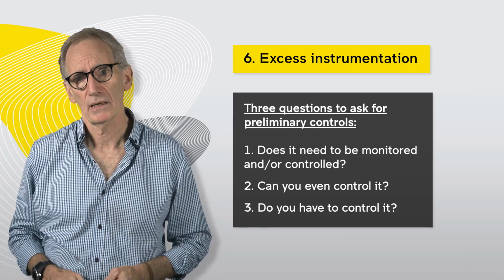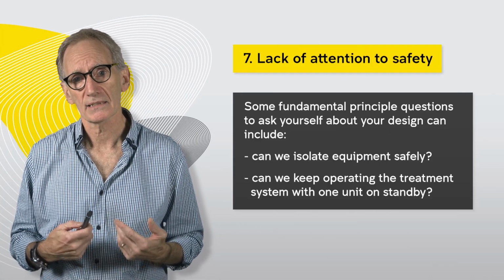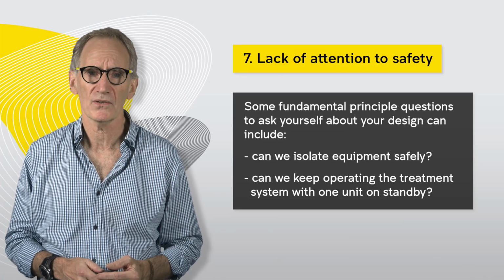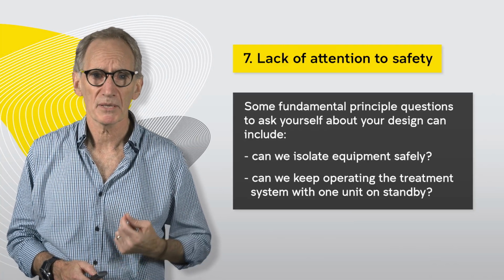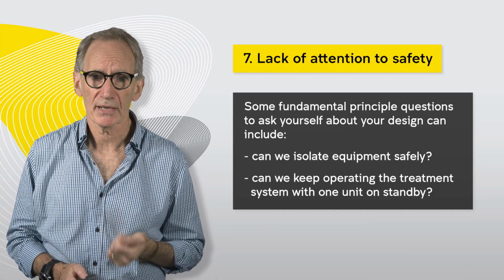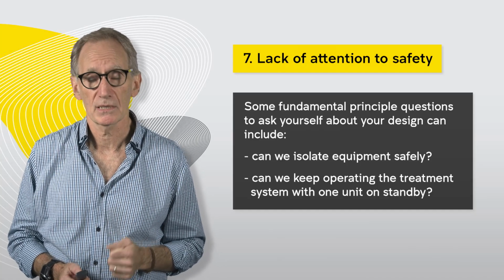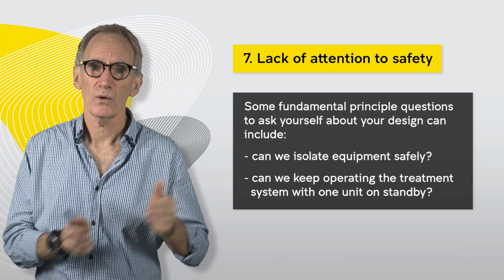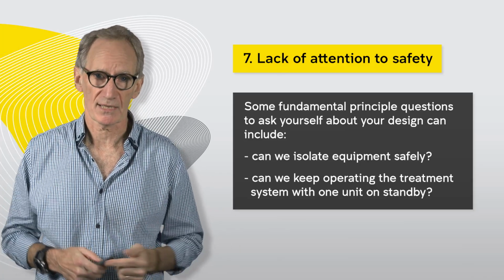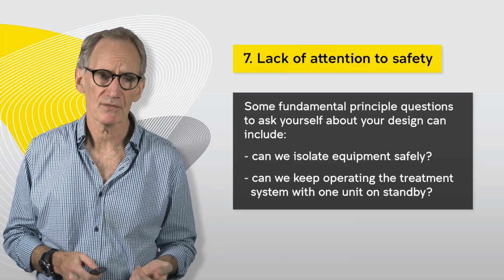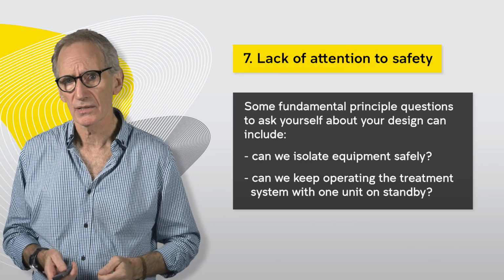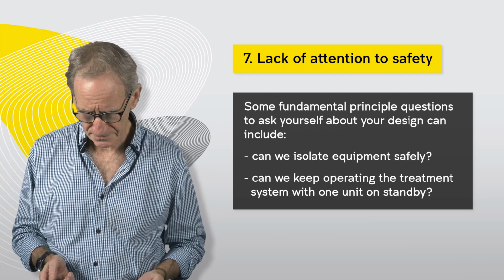Another common error I see often is a lack of attention to safety in design. And I've already talked about the importance of safety in design. But as a fundamental principle, we need to be thinking about, can we isolate equipment safely? Can we keep operating the treatment system with one unit in standby? How do we do that safely? So thinking about safety in design, or lack of thinking about safety in design, is a common error that I see in a lot of drawings.